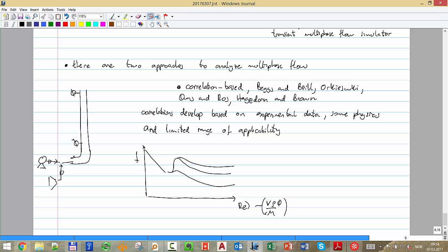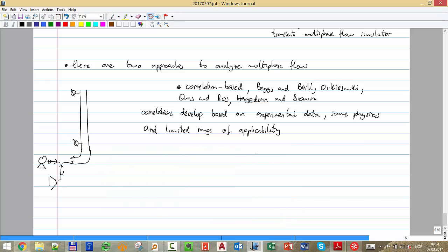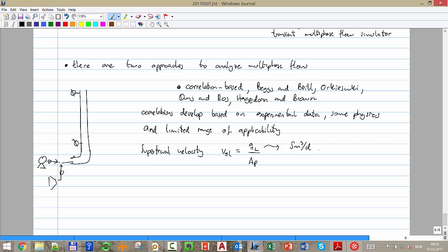Well, in this case, they found that a number called the superficial velocity, that is nothing more than V superficial velocity, Vs, and then we say of the liquid. Initially they were studying just two phases, and they say that's Q of the liquid rate divided by the total area of the pipe. And that Q, I'm asking you now, what units does it have? Standard or local? Is it in standard cubic meter per day, or is it in cubic meter per day?